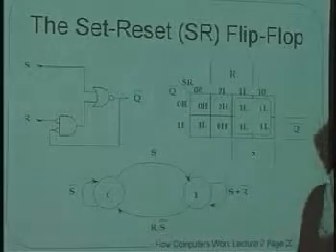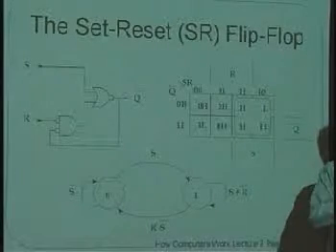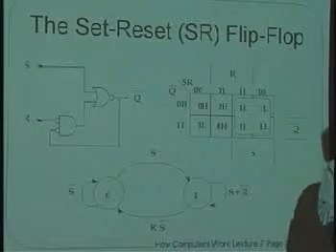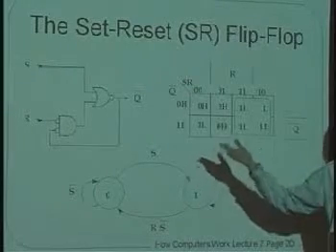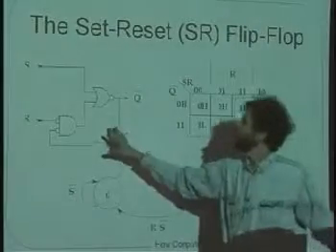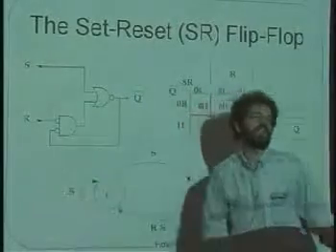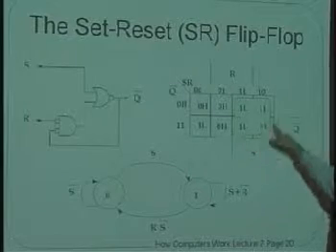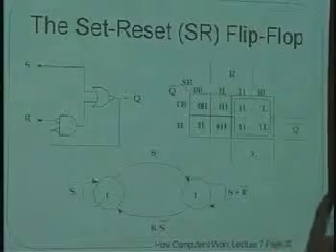So this is actually one of the first flip-flops that ever came out, sort of like a teeter-totter. If you push on this end, it stays down there. Push on this end, it stays down there. Set, reset, flip-flop. Okay? It's just a transformed version of the transparent latch that we're looking at here, and the general notion of a logic circuit with one bit of wire feedback is exactly the same. And the reason it works is, again, because the Kmap, which has this term in it, and also one more here, which I haven't drawn in, is hazard-free.